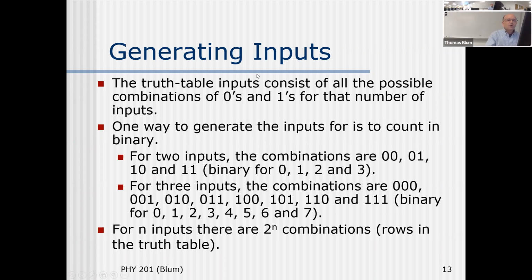Okay. So when we're making the truth table, we make all the combinations. I make all my combinations by counting. So I start at 0 and count up to 2 to the n minus 1. All that really matters in a truth table is that you have all the possibilities. I'm going to change this on you, probably next week, and produce a different order of a truth table. But in my beginner truth tables, I put them in the counting order.